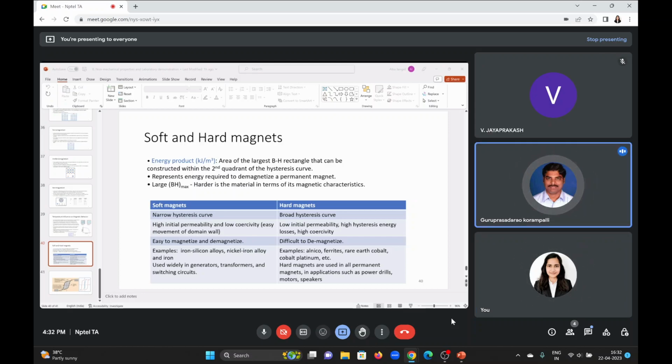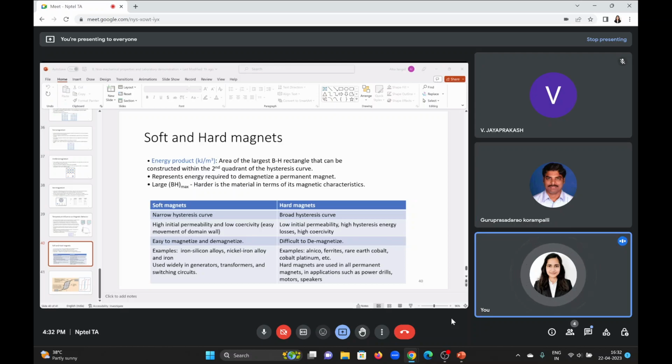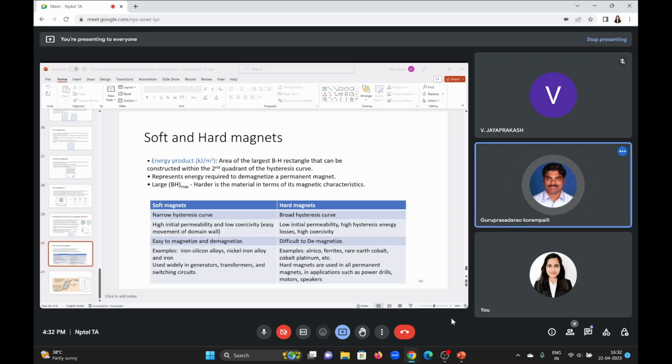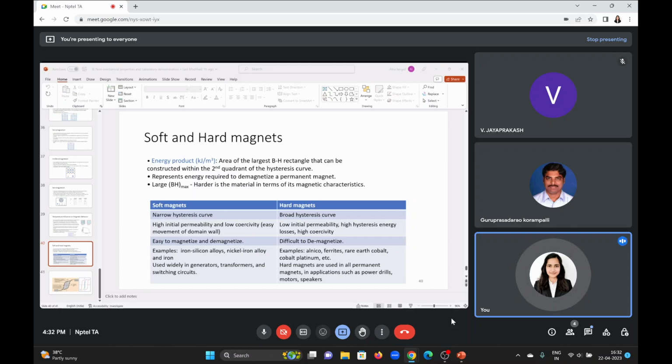1 by 2, 1 by 3, 1 by 6. Then you reduce these, so for that you multiply by 6. What does this 3 2 1 represent, madam? Your plane, or the direction that is normal to this. These are Miller indices of the plane.